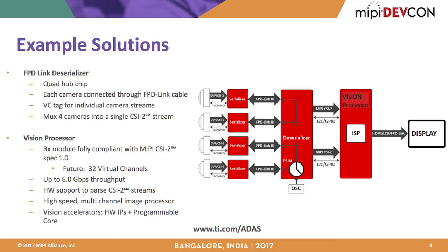But in automotive, typically the cameras are located very far away because a car is much bigger than a mobile phone. So the channel length is going to be easily 10 feet, 20 feet. In cases of big trucks, they can even be 40 feet. And channel length is a limitation of the current CSI2 protocol. So right now, how it is handled is by using a serializer-deserializer pair.